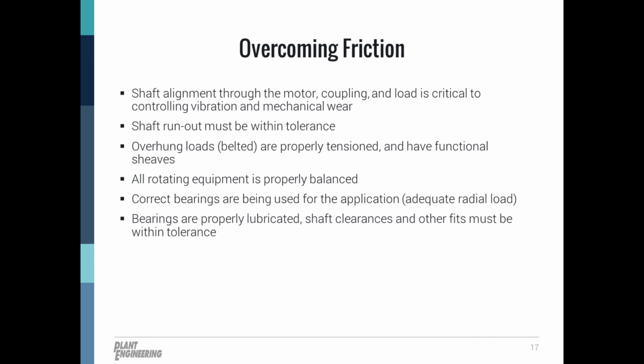This is the case if the motor is new or just been repaired. Some of these key tolerances include rotor balancing, shaft runout, bearing housing, bearing journal fits, shaft passages.